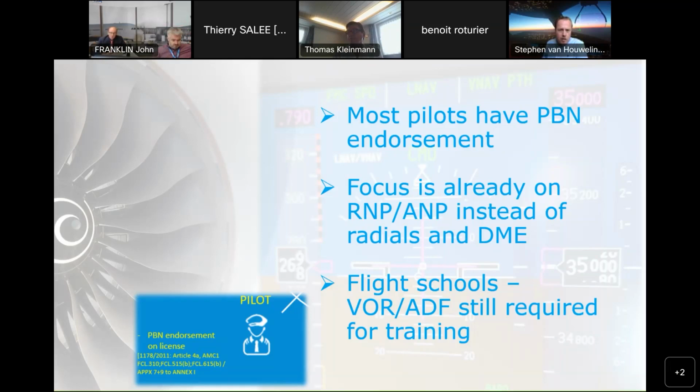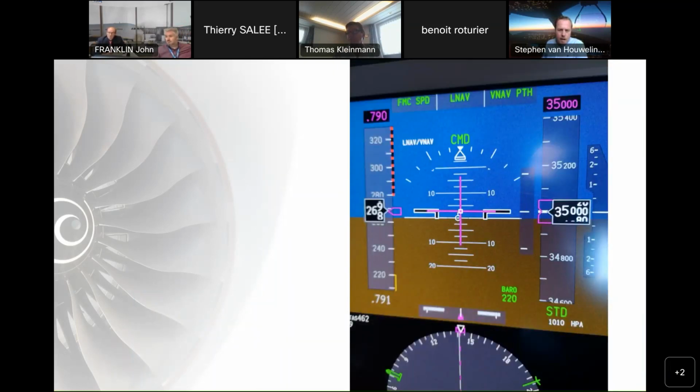And if we go to the next slide, John. As you can see on the primary flight display here, on the lower part, you see two white bars. Those white bars are normally short ones, all the way to the edges. What we did during en route, we can manually select a required navigation performance of 0.3 instead of the 2.0 we required actually. So we were still safe, of course. But we wanted to check how long it would take before we were out of limits. We put in 0.3, and this was after approximately 8 minutes.